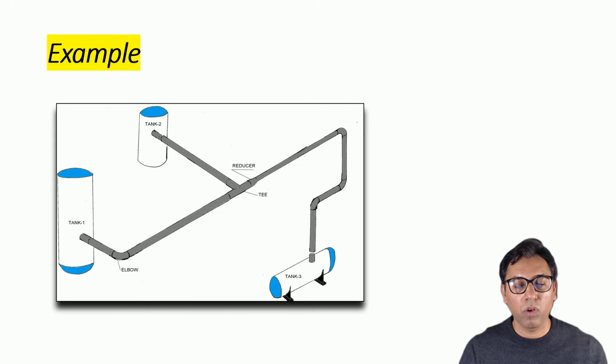These points we call terminal connections, and we will use flanges and welding to connect pipe ends with the nozzles of tanks. At this stage, pipe ends are not connected with the nozzles of tanks. Those are free ends. We will connect them in the next slides.